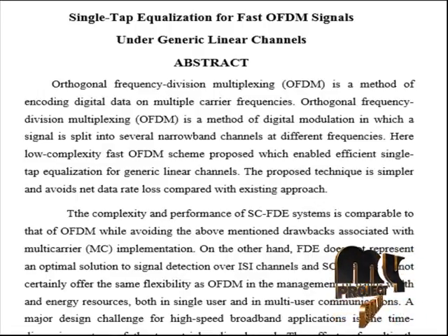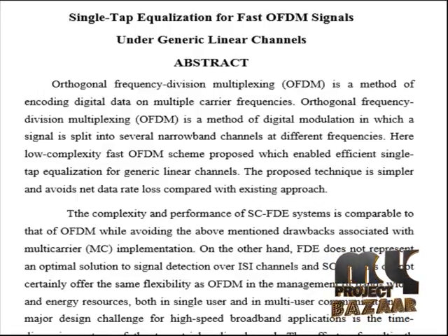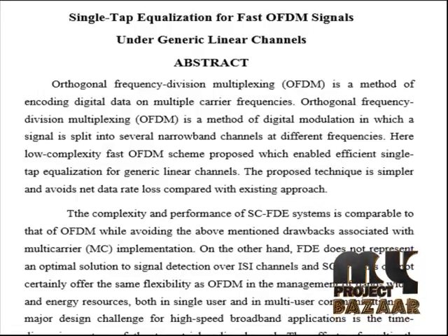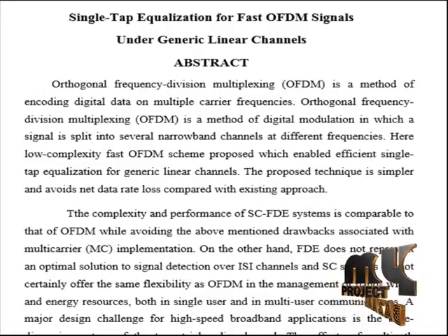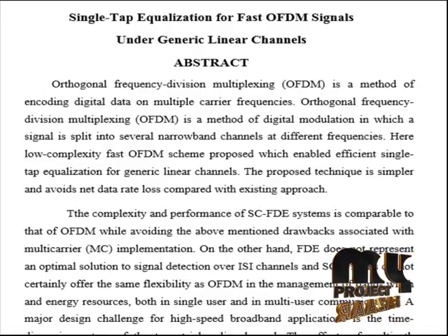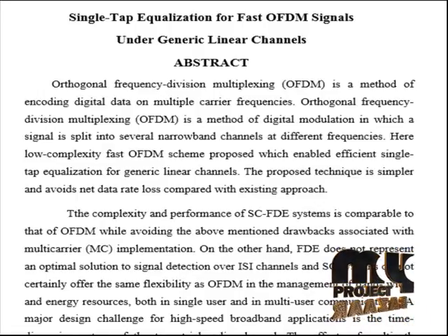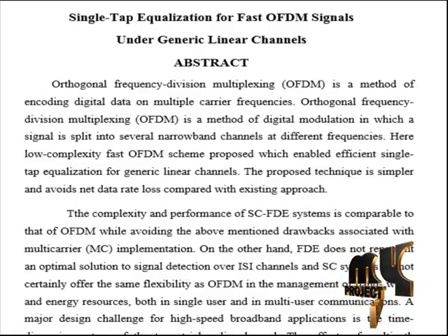To reduce the data rate losses, a DFT of double length is used, that is, n subcarriers are demultiplexed by the DFT on a 2n point. Zero padding is added. The guard interval is added at the transmitter side. Zero padding pads the guard interval with zeros. The proposed scheme achieves better performance under wireless frequency selective fading channels.